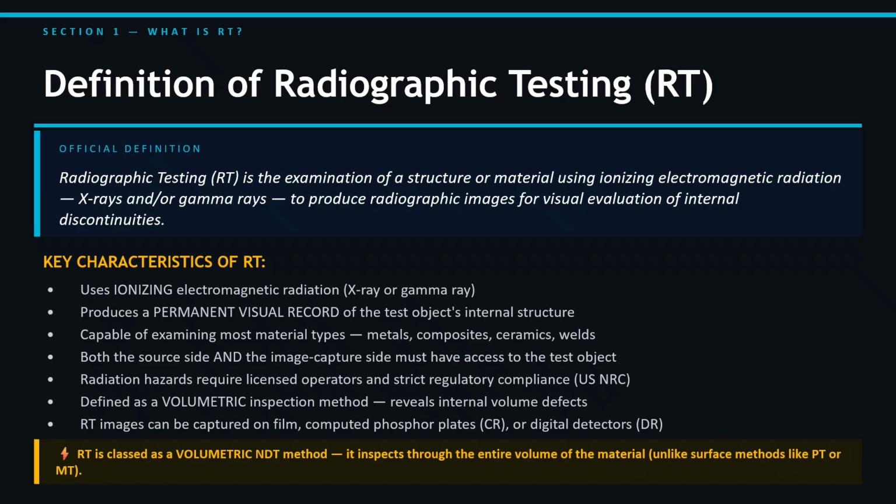And remember the distinction between a discontinuity and a defect. Radiography may reveal a discontinuity, but whether it is acceptable or rejected depends on the applicable acceptance criteria. That distinction is critical for anyone working toward Level 2 or Level 3 responsibility.